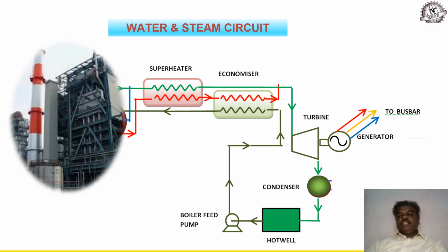The boiler is basically a pressure vessel meant for raising steam by burning a fossil fuel, namely coal. The steam that is generated in the boiler will be of wet or dry state. Normally, in a thermal power station, wet steam is not desirable because the water particles that are larger than the steam could go and hit the turbine blades like bullets and can cause damage to the turbine blades.